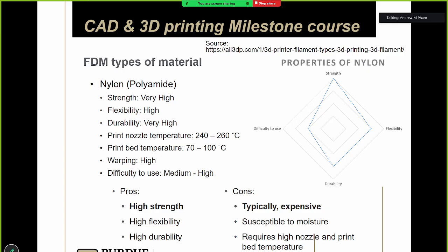So I took the old broken bolt out that I snapped, which is definitely my fault. I took some measurements and I 3D printed a carbon fiber nylon drain bolt, and then I screwed it on, and now my car works again, right? It took me to work, and it's been good ever since, no leaks. So it's pretty awesome that you can do that with 3D printing these days.